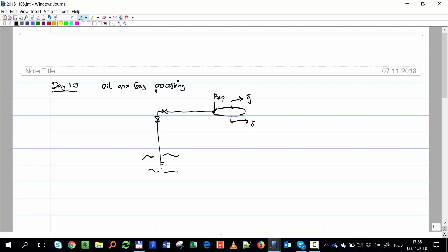The only thing where it is important is the oil-gas ratio, how much oil and how much gas you have. That depends on the surface process. So just to say also that if you're making an equilibrium analysis on a well, you have to include somehow the surface process, and that enters indirectly in the black oil tables.